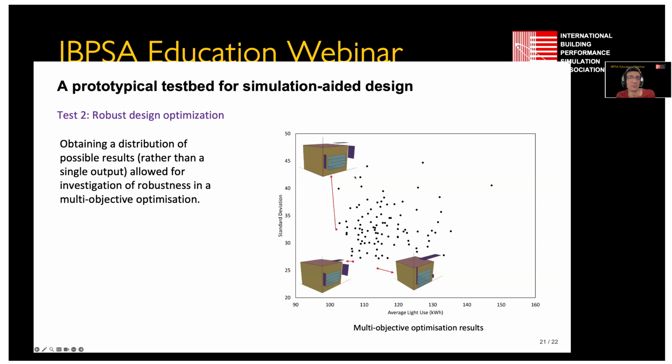And we saw that with the specific designs, for example, we could minimize the average energy use, whereas other solutions have been more effective in enhancing the robustness of our design. So in reducing the possibility of unpredictable performances, right? Or you may have solutions that do rather well in both areas. So these are all possibilities that we have opened up because we have data-driven stochastic occupant behavior models that capture these nuances of occupants' interactions with building environmental control systems.